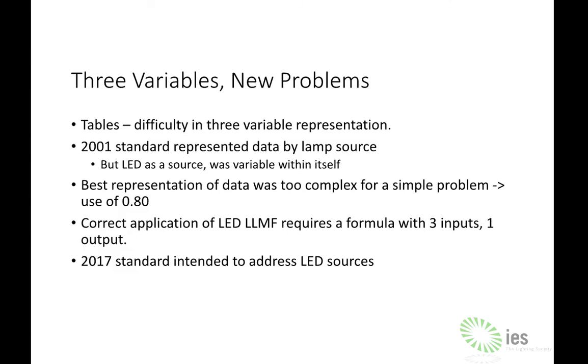Like, maintenance factor is ultimately a tiny bit of what we do. It's such a simple problem. And no one's really applied too much thought to this thing. So as a result, we've just used 0.8 because it'll be okay overall. Day one, the client's not going to complain because it's going to be too bright. And it's really down to 2, 3, 4, 5, 10 years when we start to have problems, and then it's someone else's problem, right? That's why we use 0.8.